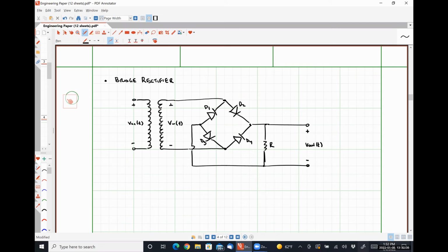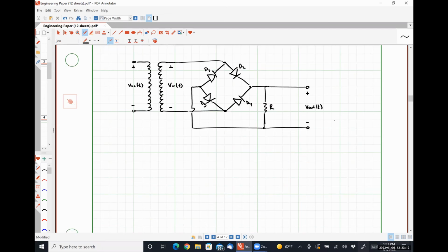So we double the number of diodes. We wind up getting a very similar output signal, okay? Diodes are cheap, on the order of nickels or whatever, 25 cents to $1 for really good ones for specific applications, whereas center tap transformers are tens of bucks and stuff like that. So this is a much cheaper implementation, but it's a little harder to understand exactly what's going on. So let me draw my plot here, and we'll talk our way through the input-output response.